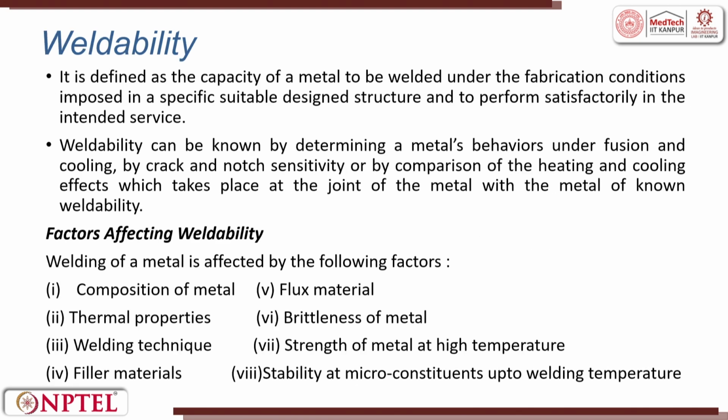Now, the important terminology which comes is weldability. Can this material be machined? Machinability. Can this material be cast? Castability. Can this material be forged? Forgeability. So, can this material be welded? Weldability. It is defined as the capacity of a metal to be welded under the fabrication conditions imposed, in a specific suitable design structure, and to perform satisfactorily in the intended service.